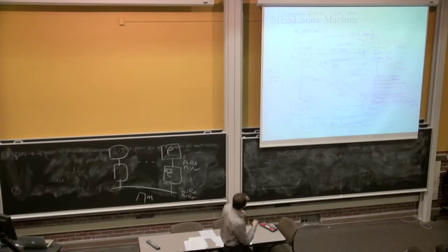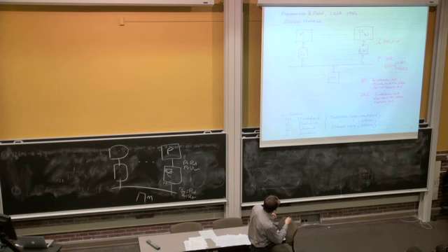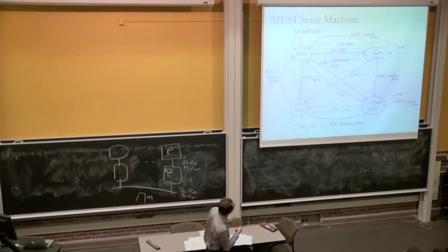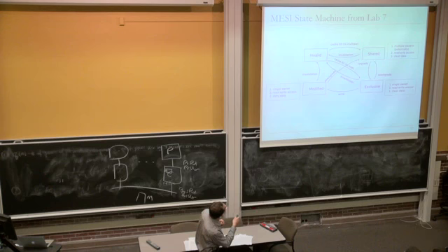Okay. So I've also given you 2 additional signals here. You can actually divide bus write into bus invalidate or bus read invalidate, if you will. Bus invalidate means invalidate the block, but you already have the data, so other processors do not need to supply it. And bus read invalidate means invalidate the data, but I also need the data for the cache block. That means other processors know to supply the block. And you can look at the state diagram to figure out when it's used. So this is the state machine that you will actually build in Lab 7. It's very similar.